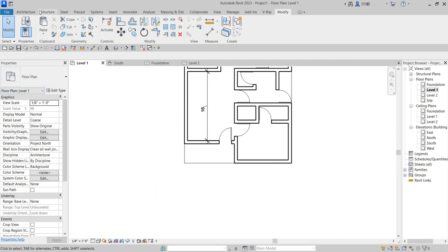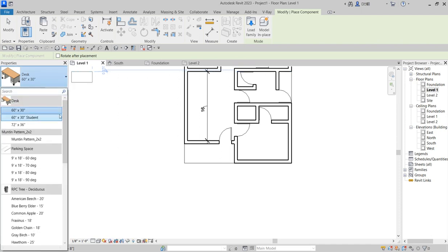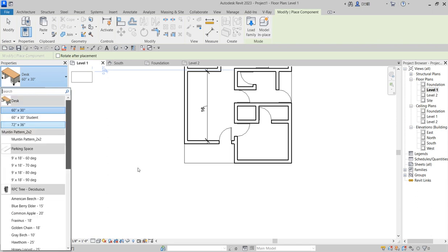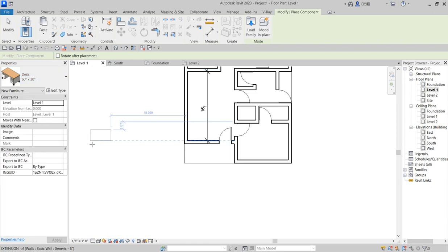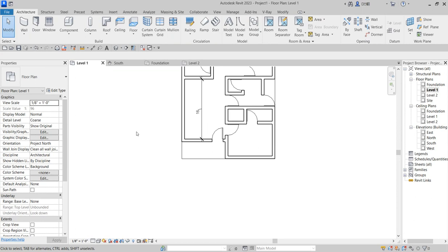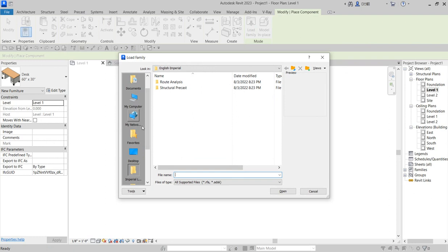So you go back to architecture and you click on components. And how do you do that? You search for more components. Are they okay with you? Do you have them? Do you need them? Are they existing? If they are not existing, what are we going to do? The templates that are here are not much. So if you have a place where you keep templates, you can use them. You click on components, and you say load family, according to the component you have chosen.